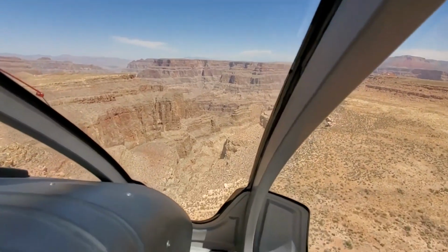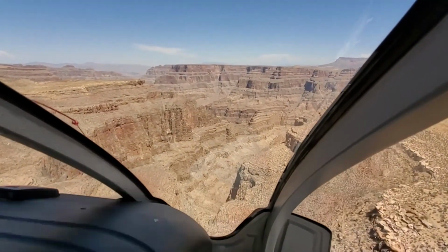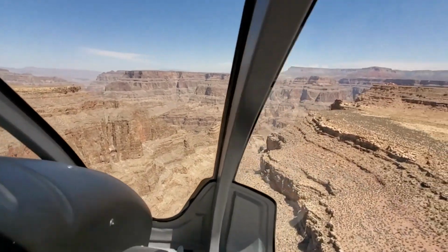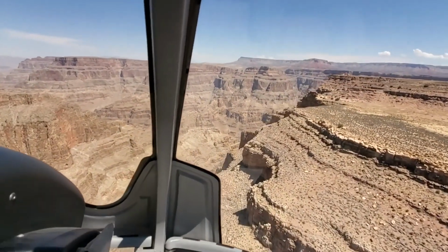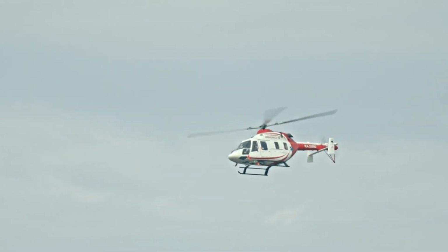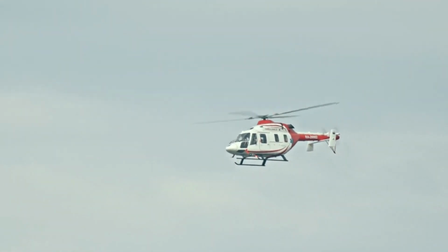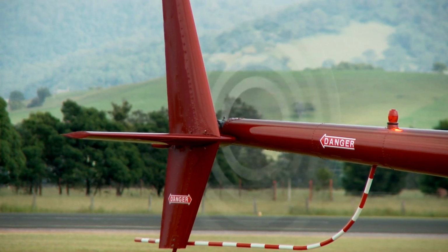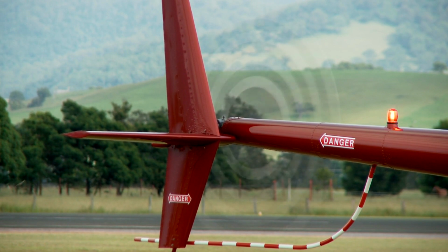To bring this aerial ballet to a pause, the pilot applies cyclic pressure in the opposite direction of movement, holding it until the helicopter gracefully comes to a stop. As the motion ceases, the cyclic returns to neutral, preventing movement in the opposite direction. Alternatively, sufficient opposite cyclic pressure can be applied to level the helicopter, allowing it to drift to a stop.